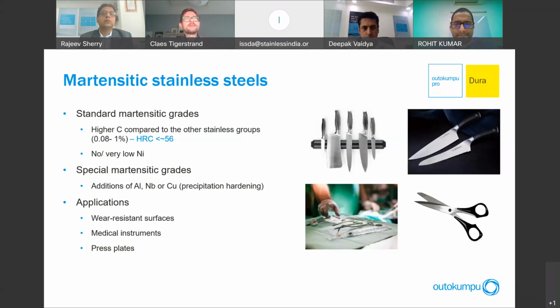Of course, 316 is most commonly used for outdoor environments, but 304 can also be used if it's less corrosive. But 304, 316, and the austenitic grades are the best ones to use if we're looking at surface quality as well as weldability.